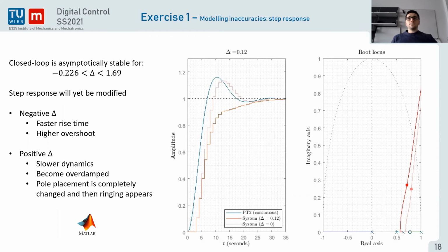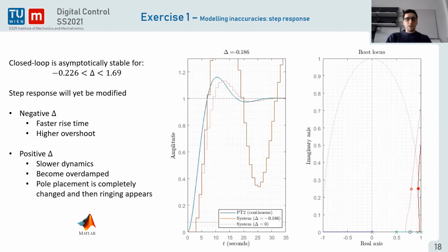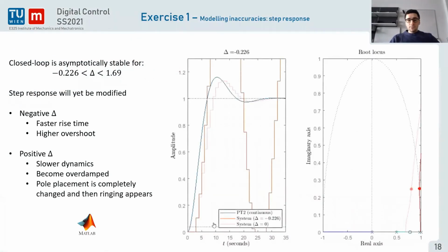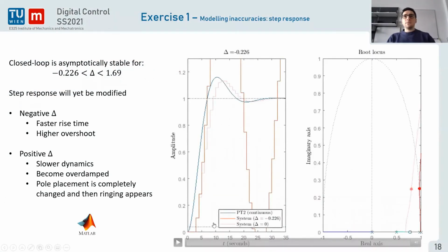So I know that for some of you, everything is pretty clear because you already did it in continuous time. But still, I guess it's quite good to have a quick recap. And you can see that in discrete time, the only thing that's different here so far is that you can have ringing if one pole is close to -1. And the other difference is how to compute the steady state gain, which is for z equals 1, denominator z equals 1, and that's s equals 0, so not z equals 0.